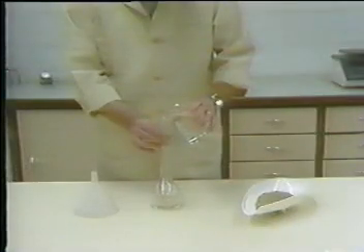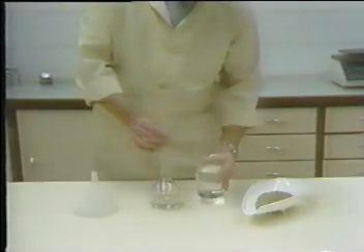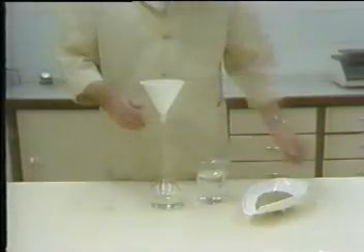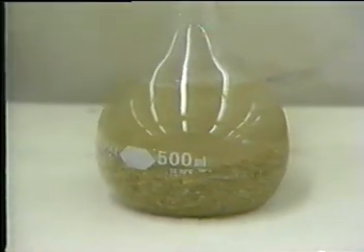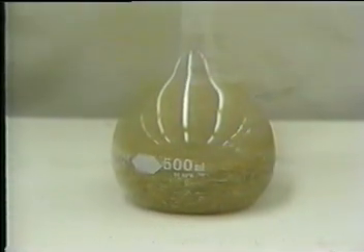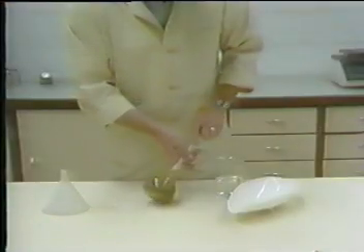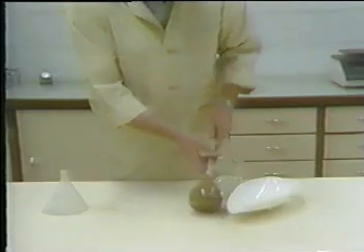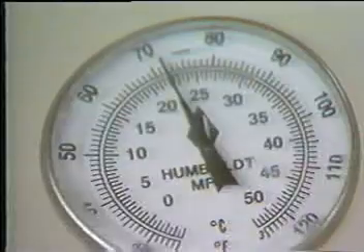There are several ways to determine the specific gravity of fine aggregate. Here we will use the volumetric flask method. Partially fill the flask with water. Pour 500 grams of saturated surface dry aggregate into the flask and fill it with additional water to approximately 90% of capacity. Roll, invert, and agitate the flask to remove air bubbles. This will take about 15 to 20 minutes.